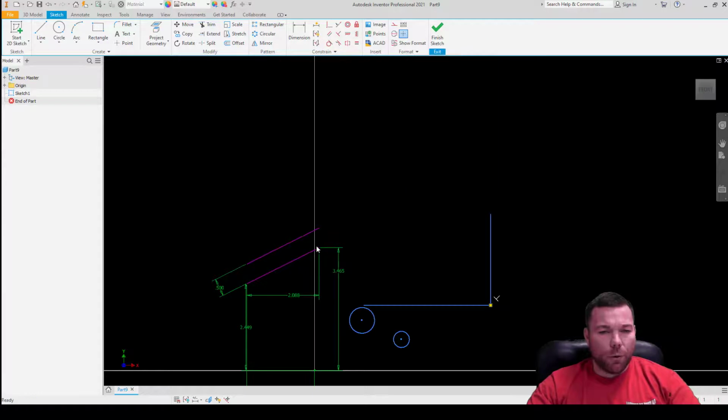We went over vertical. Vertical just aligns things vertically. Now, the way I use vertical and horizontal is usually not in this fashion. The way that I generally use them is to align circles. So I'll be drawing something, and generally I'll want to align a circle center point with maybe the end of a line, or maybe the origin, or something like that.